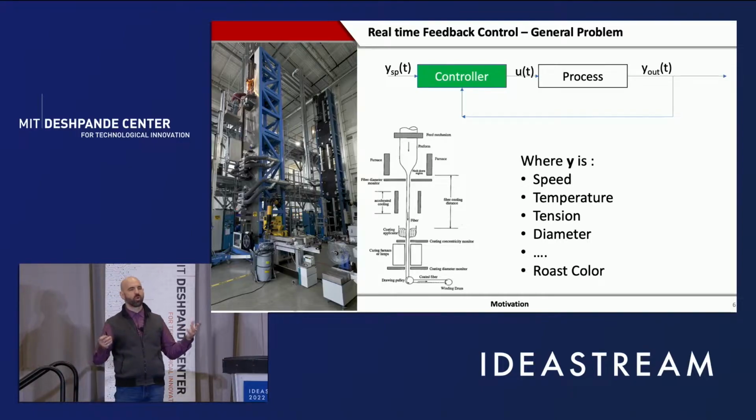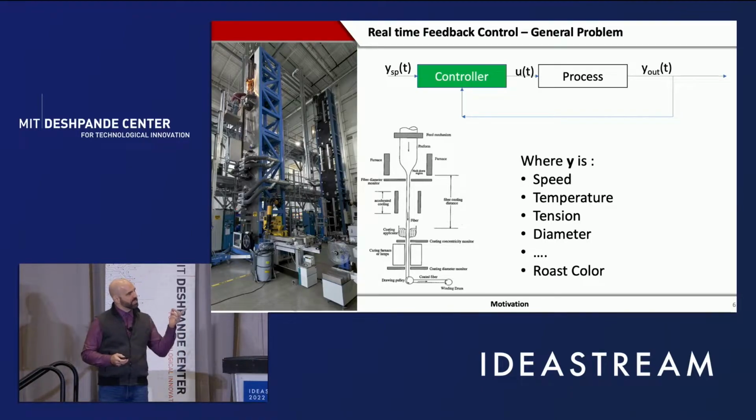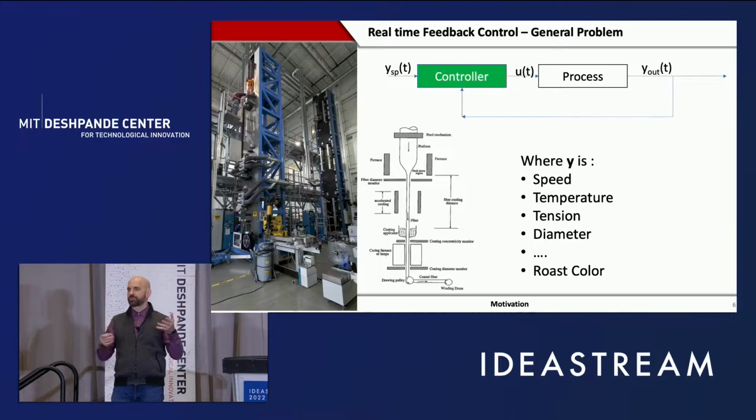It's a workhorse engine, it works very well. Basically, this controller takes the error signal, the difference between what you want and what you're getting, and decides to apply control effort that's either proportional to your error, proportional to the derivative of your error, or proportional to the integral of your error.